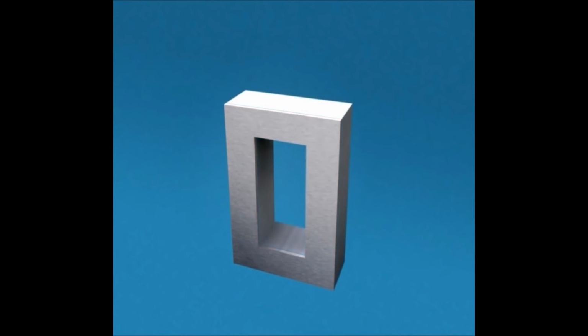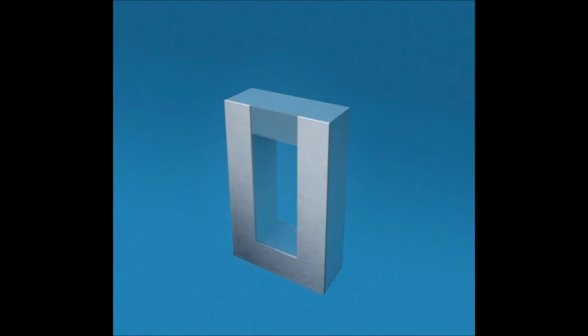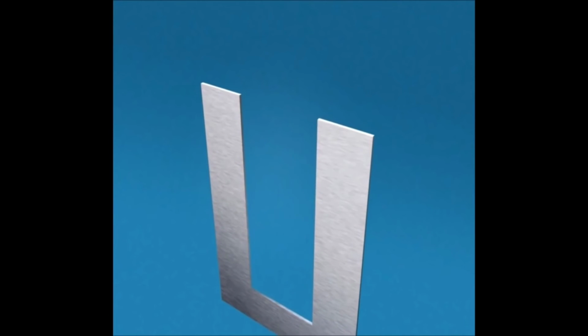Laminations are made of a highly permeable material, that is silicon steel. These laminations are assembled together to build a solid core. The resistivity of the steel sheet itself is high, reducing the eddy current losses while making the laminations very thin.